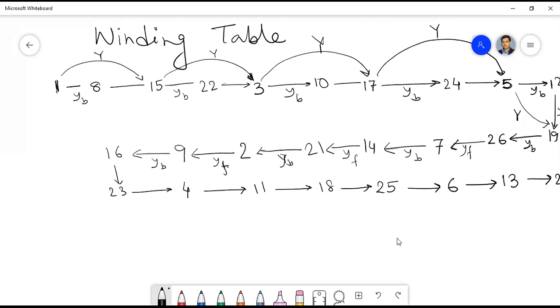Now, another difference, you can say the disadvantage of lap winding. I mentioned in the last class that the lap winding may have different voltages in the different parallel paths. If the voltages are different in different parallel paths, I discussed how the circulating current will flow.